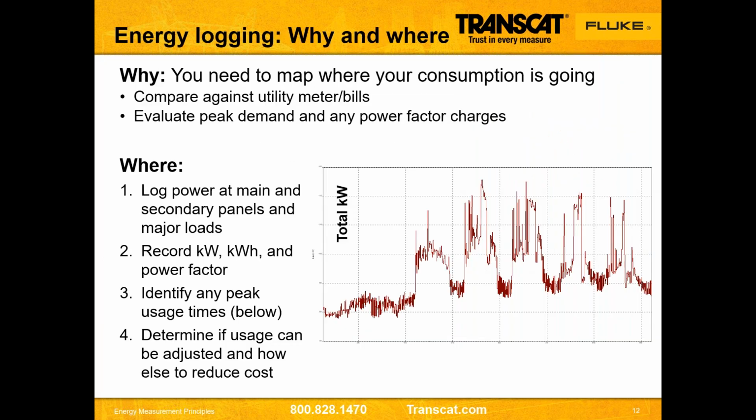So we would actually log or record data over time. And the idea here is we want to look at usage over time, because there's a rhythm or a cadence in terms of usage in every plant or every building. And you'll have peak times, let's say during manufacturing hours, between 8 o'clock in the morning and 5 o'clock in the evening. And then you'll have off-peak hours after 5 o'clock, where I might still be running production, but my usage starts to drop because not all the machinery is running, and maybe even less on the weekends. So if we start to get a rhythm or a profile, we can figure out how much usage we're using at different times of the day and what types of loads are on during those times.